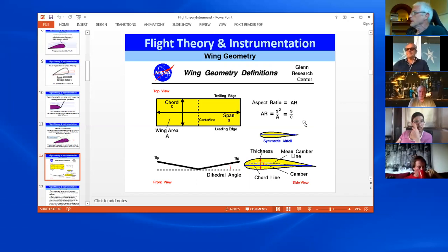And it doesn't really go into much detail, but the significance of it is the higher the aspect ratio for a wing, the more pilot input is required to fly it, basically. You take a low aspect ratio wing, you can stick a sack of potatoes on and shove it off a hill and it will fly quite happily. School wings are designed so that you don't have to put a lot of input into it. It will self-correct. It's very stable. It's not going to fall out of the air easily. It's not going to get thrown around as much.